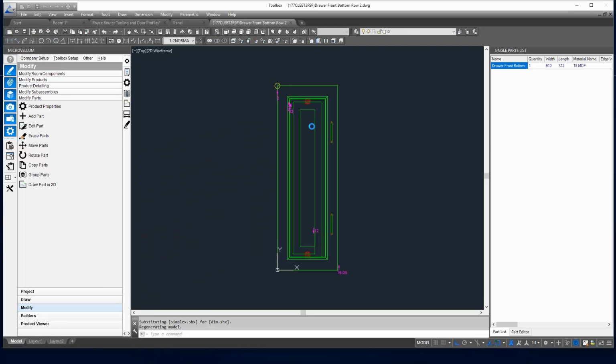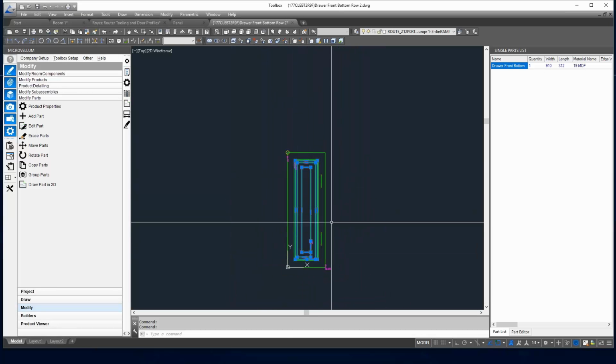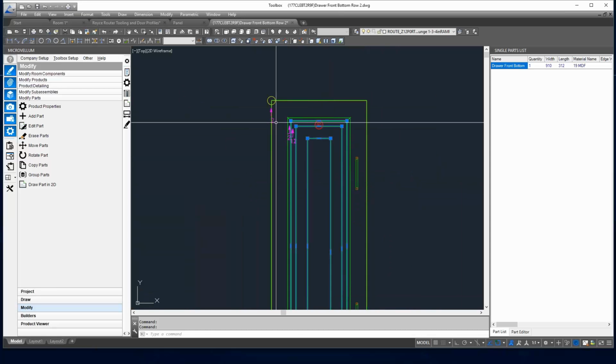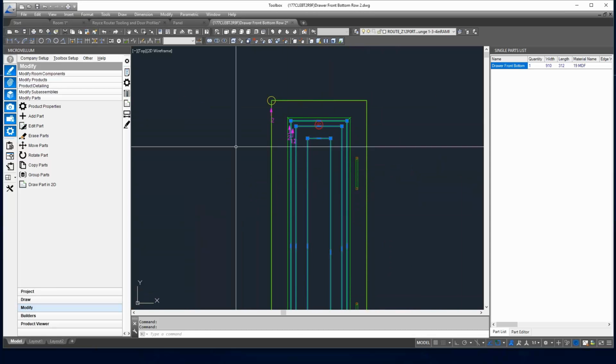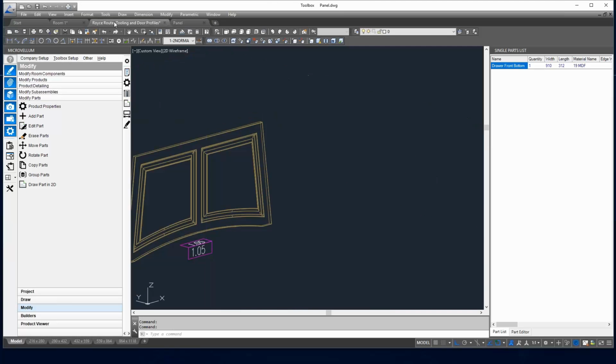And so it's going to create all the machining that it needs in order to pocket away all the material. So here you can see I've got this tool coming in, and it's going to pocket out the entire center of my panel going right out to the edge, and then I'm coming in with a 1/2-inch tool and an 1/8-inch tool to clean that up and leave just that 1/16 radius in the corner and give me the finished detail that I'm looking for.